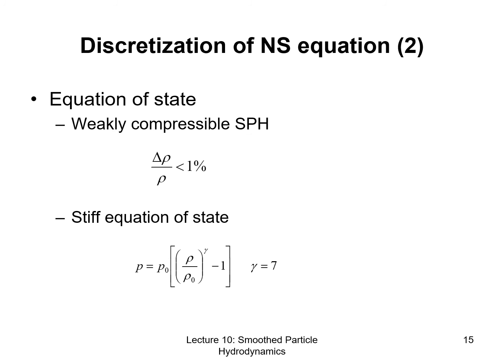Very often we approximate incompressible flow with SPH. SPH usually doesn't do the same as traditional CFD, where people solve a Poisson equation related to the density field. In SPH, we use a so-called weakly compressible approach. That means we assume the flow is weakly compressible, so the density variation is not big.